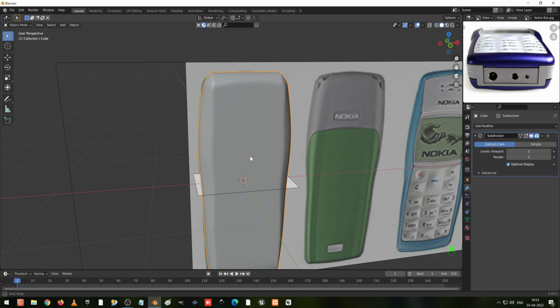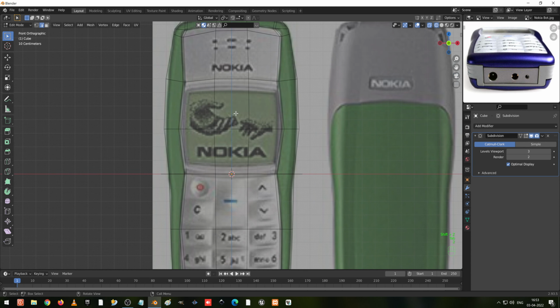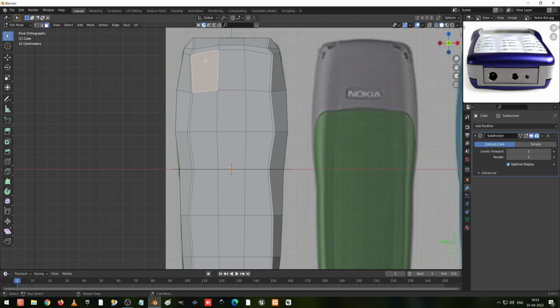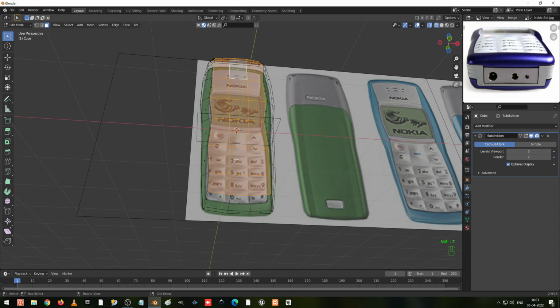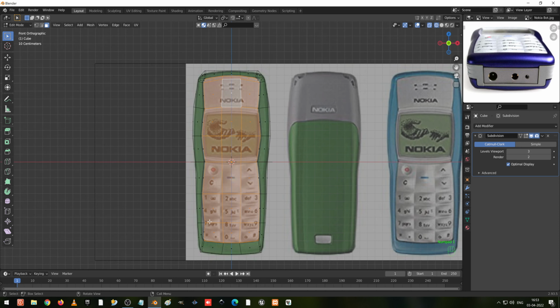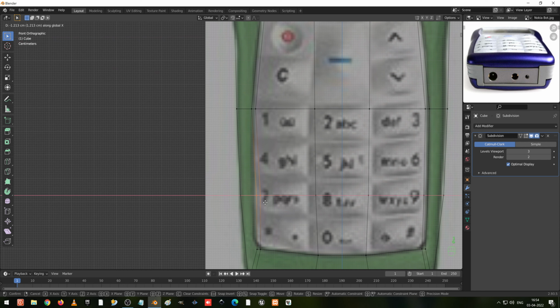Actually, the design which is coming inside doesn't look the same, right? So for this, what I'm going to do is go to the front view, press Shift D and go to the face selection in wireframe. Select these faces using a circle select. So go on, see it in front view. Okay, only this is still having issues. I can move it, G X to move.